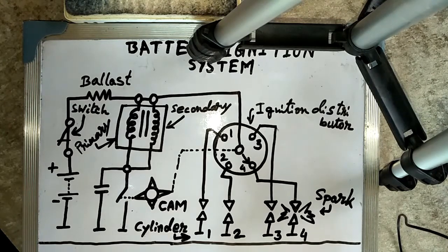Such current charges the condenser to a voltage much higher than the battery's voltage. The condenser then discharges into the battery, reversing the direction of both the primary current and the magnetic field. The rapid collapse and the reversal of the magnetic field in the core induce a very high voltage in the secondary winding of the ignition coil.